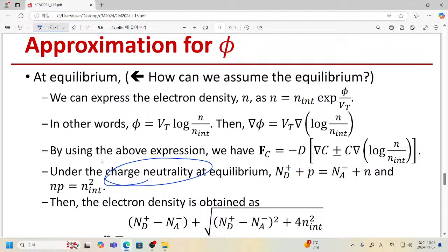When you have a p-n junction, usually you have a depletion of your charge carriers, electrons and holes, and you really have space charge. However, in this approximate approach, the developers of this dopant diffusion simulator assume charge neutrality.